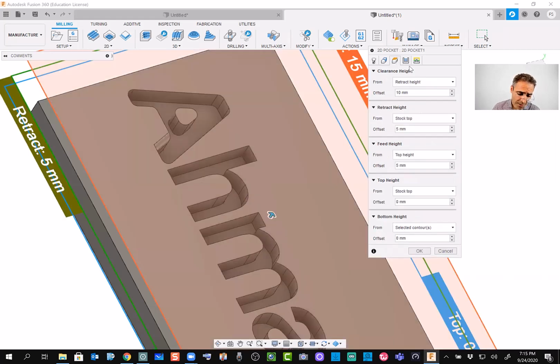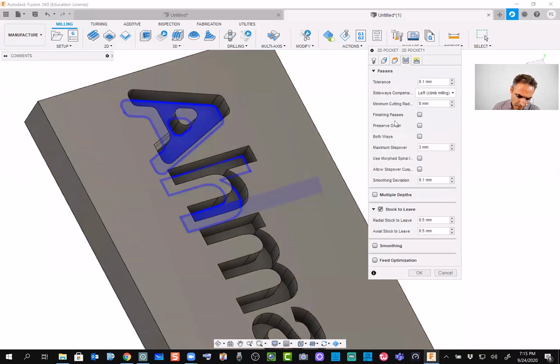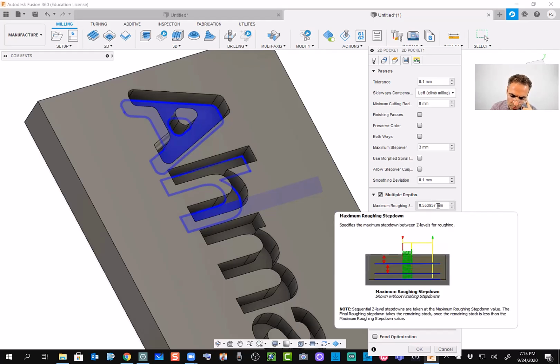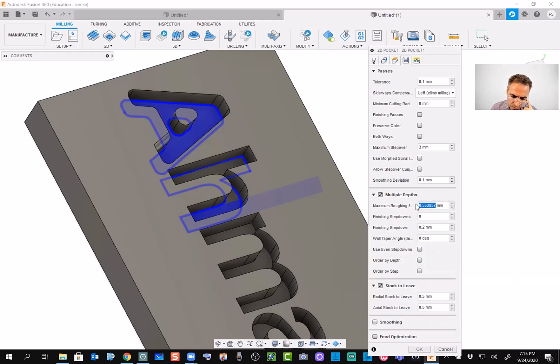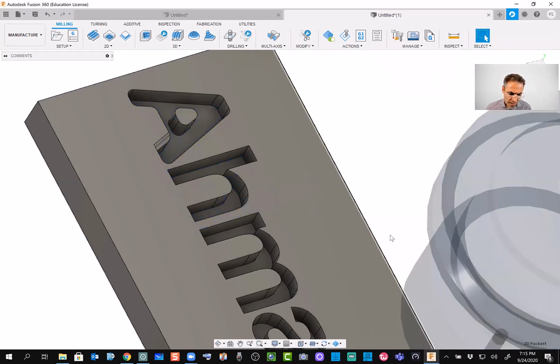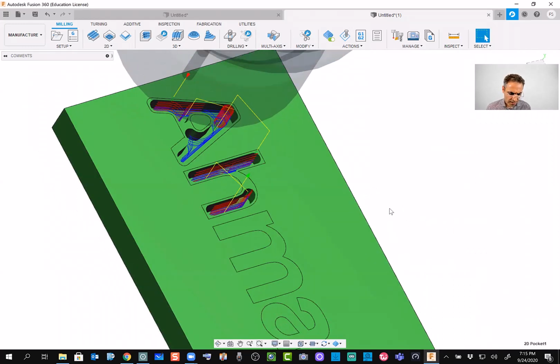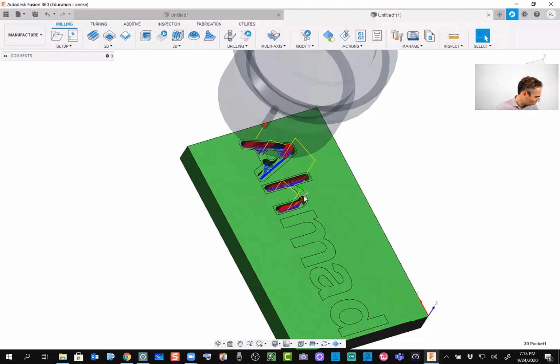Okay, what Ahmed you ask is the multiple step, right? This multiple step, this is the one here. So I select multiple steps rather than doing it one shot. Now this is where we can select. So instead of 0.5 millimeters, why not we do like 1 millimeter as a stepping down. And then we press OK. Okay, so let's see what happens. It gives us the toolpath.